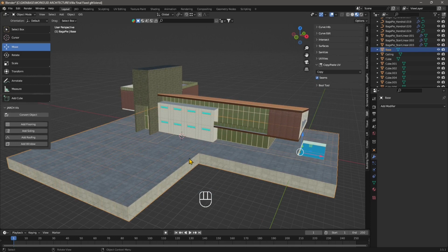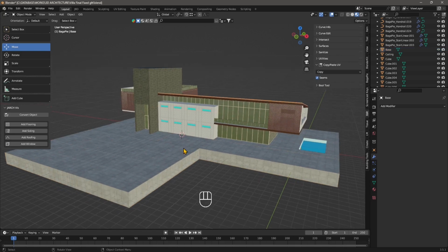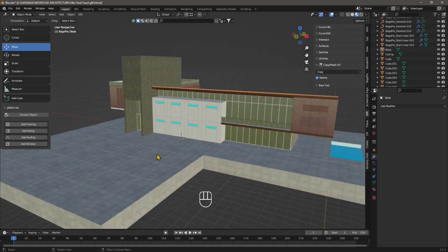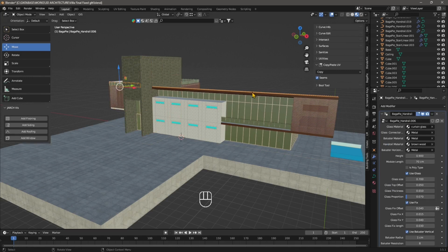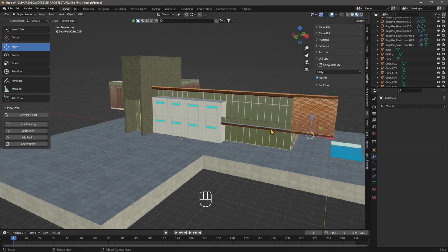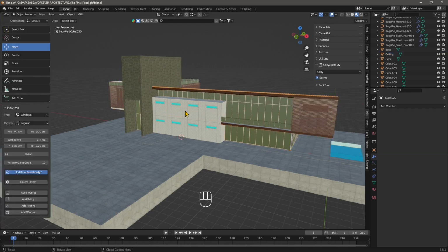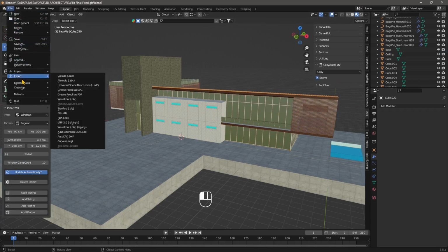Now this one here, the base, I think it doesn't have correct UV mapping. Mapping is really important, but in architecture we can find a solution also in Twinmotion. Still, make sure that not only your materials and textures are okay, but also the mapping. Everything needs to be correctly mapped. Otherwise, it could give problems in Twinmotion, but I'm going to show you how to solve it.